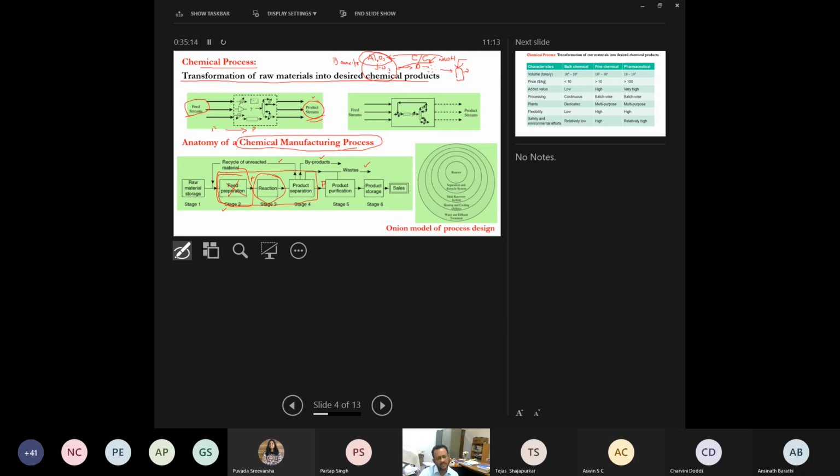Okay. So once what will happen? The digester is operated at very high pressure and temperature conditions. First, it has to be sent to the separators. Okay. So here your flashing, or you can say flash drums. So your vapor and the liquid streams are separated here. So the liquid streams, once separated, go to desilication tanks where the sodium silicates are removed.